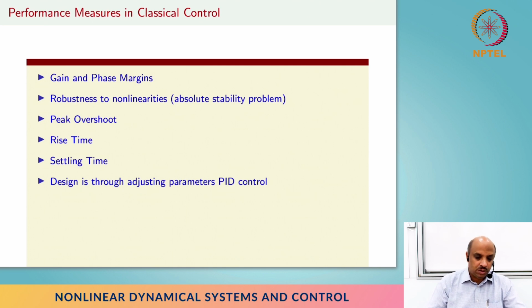So you will take the sensor output, either multiplied with some factor or integrate it for a while, continuously integrating, and then multiply that by a factor and take a derivative, right? And it has been shown that for various classes of systems, the PID control is quite good in terms of ensuring that the target value is reached and things like that.